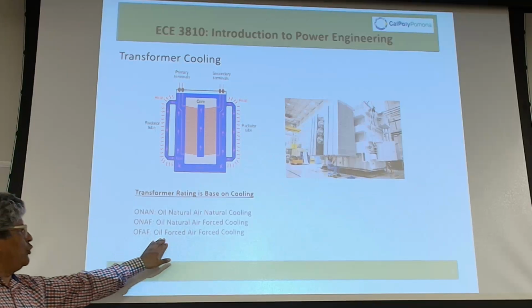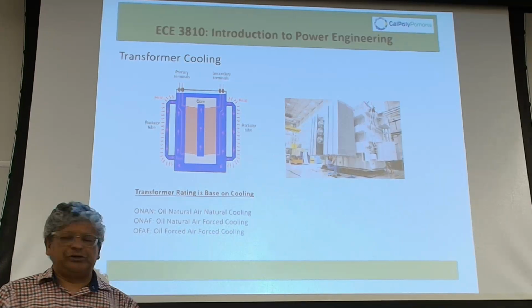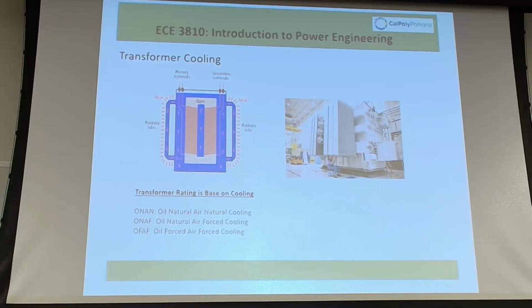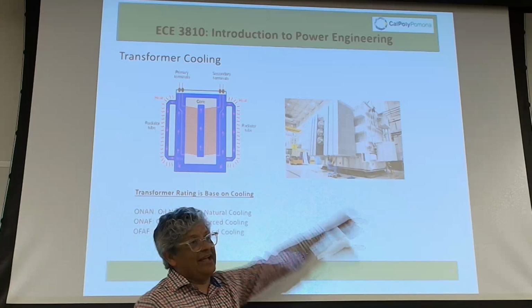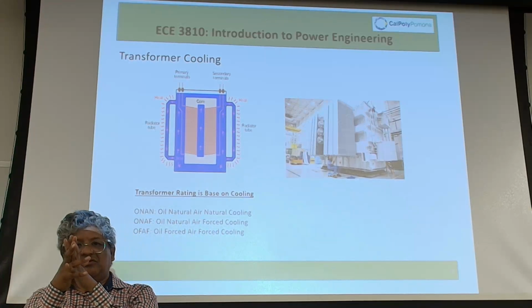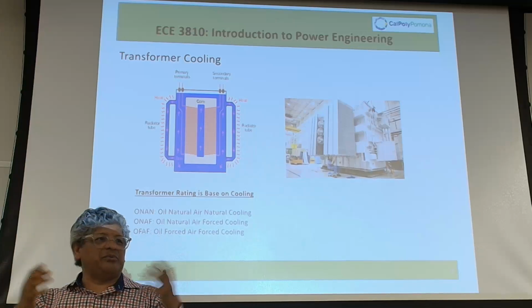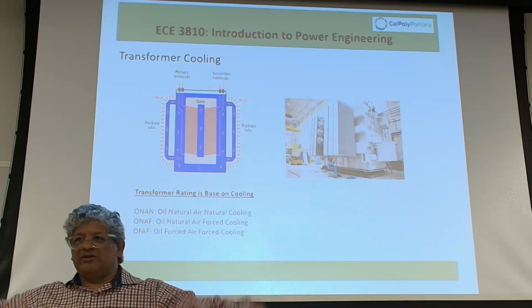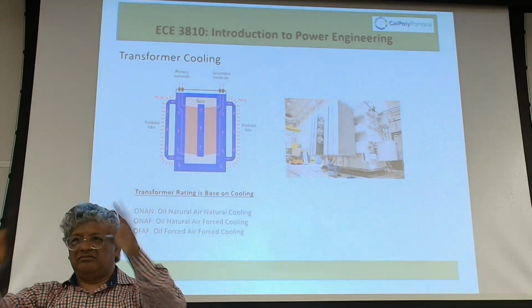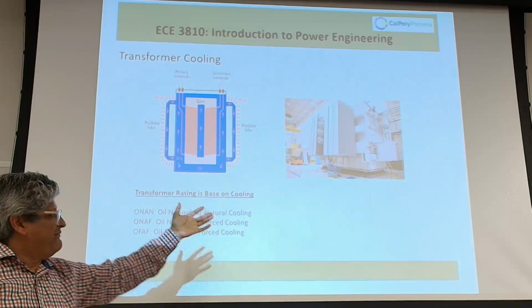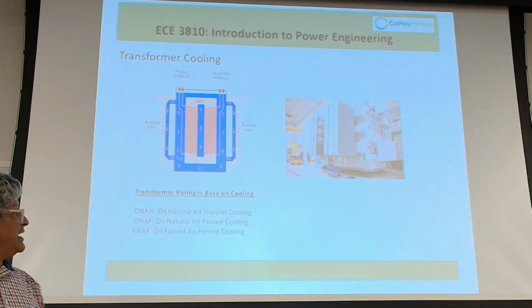And then you can have oil forced and air forced. In other words, the tank has a pump circulating oil to these radiators, and then you have fans blowing on the oil. Kind of the same concept as in your car, right? You have a radiator, and the water is cooling the engine, and then you have the big fan on your car. It's a very similar concept.